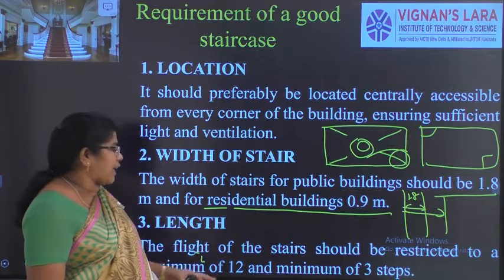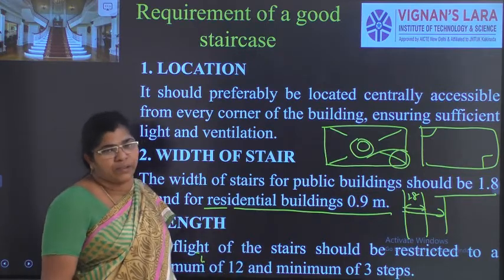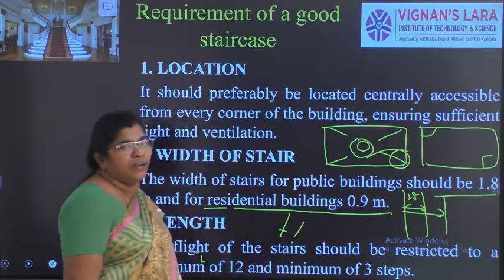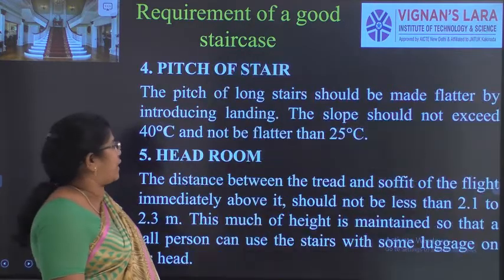So the length of the flight is restricted to a maximum of 12 and a minimum of 3 steps. Okay. So the number of steps in a flight should not be more than 12 as per the norms. In some cases it can go up to 15.